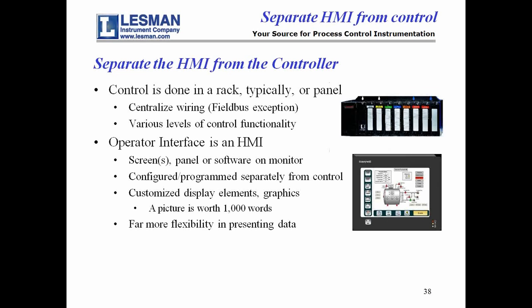Now, original PLCs were really just discrete I/O, but in the last 15 years, most PLCs have adopted some form of analog control. They're always rack devices with modular I/O. I shouldn't say that, there are shoebox PLCs out there, but basically they look like the one on the bottom of the screen down there. They're blind. I mean, a PLC itself is blind. It has little diagnostic LED indicators on it, but it doesn't really give you any process information.